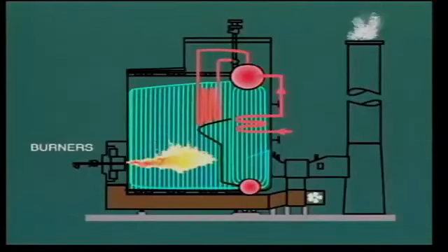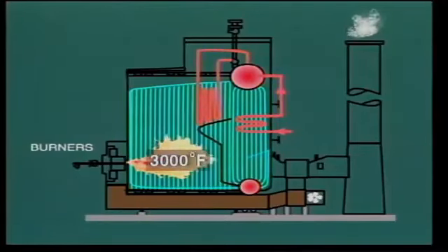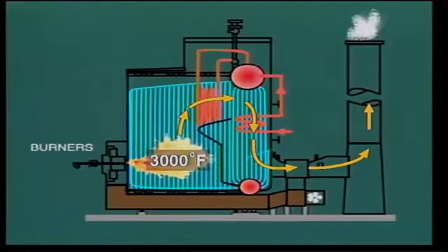As atomized fuel oil and air enter the furnace, they burn with a bright flame when conditions are correct. Close to the burner, the flame is intense, with a temperature of about 3,000 degrees Fahrenheit. As the flame moves further into the furnace, it turns upwards towards the superheater, where eventually flames no longer exist. The hot combustion gas continues on through the boiler convection pass.